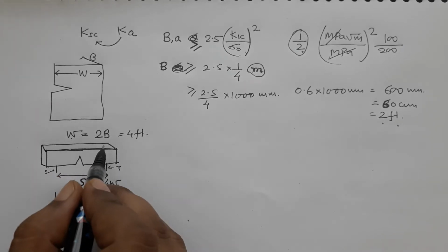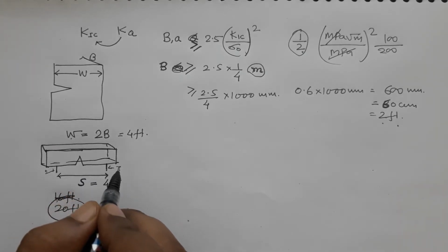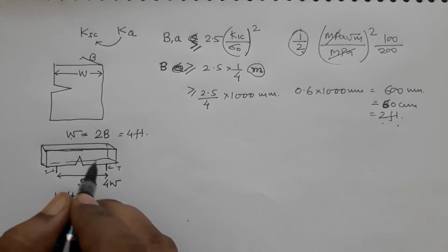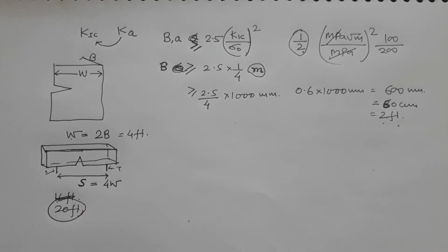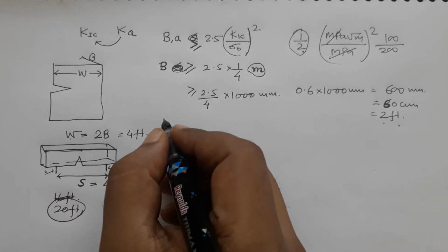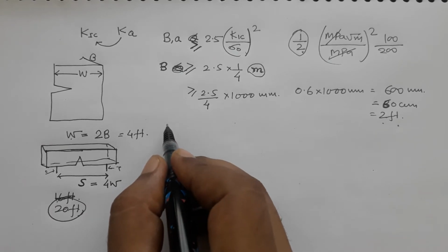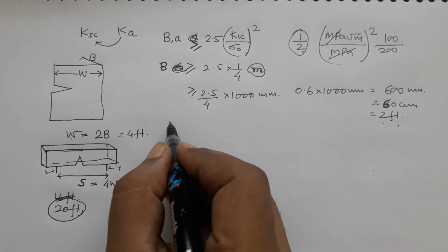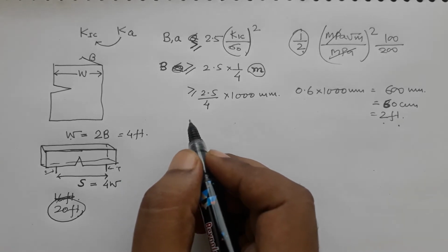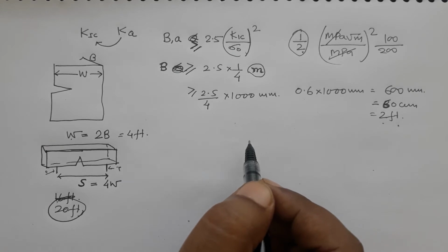You can test this kind of sample, and people have tested such big samples, but for that you probably have to do the whole casting of the steel to form this sample, and then who will carry it, and so there are a lot of problems, and doing this is not practical, right. So, why are we having this kind of situation? We are having it because we have a parameter which only works when the material deforms in an elastic manner. If it deforms in a plastic manner, we do not have a real parameter which can describe the fracture toughness of the material, okay.